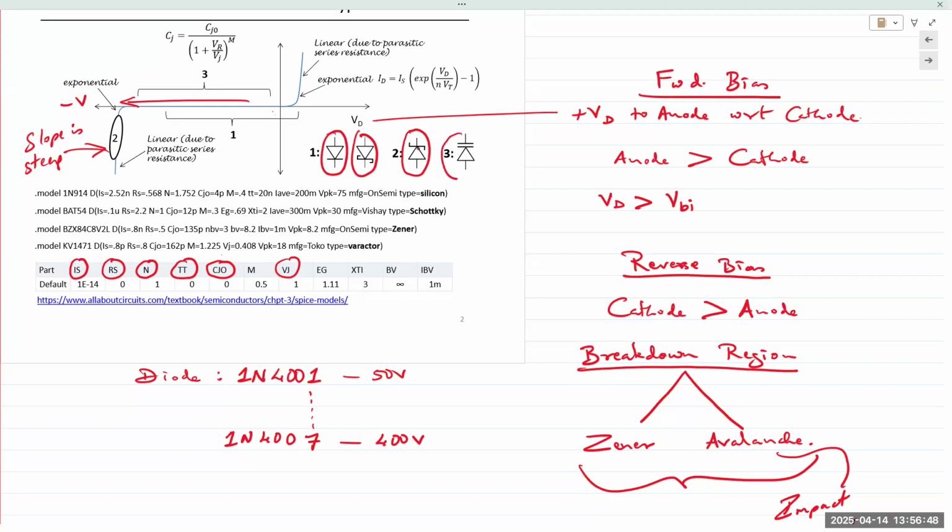And then this one is a varactor diode. A varactor diode, as you see here, has a capacitance represented at one end, which is basically the end of the cathode. So if you see a capacitance symbol at the cathode end of a diode, that represents a varactor diode. The property of a varactor diode is that you can control the capacitance by the input voltage that is being applied. Okay, and there are specific applications for these varactor diodes and Schottky diodes.